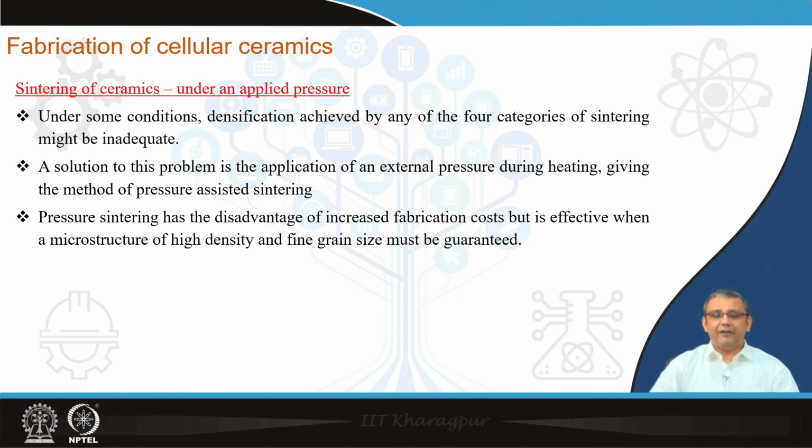Pressure sintering has the advantage that because of the applied pressure, the driving force for sintering is increased, and as a result the sintering is carried out at a lower temperature, and less time at that high temperature is required. This has benefits because a combination of lower temperature with less time will lead to less grain coarsening, which can lead to better mechanical properties.